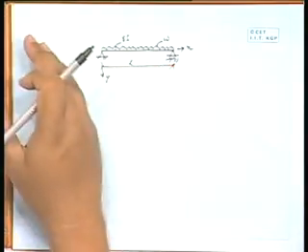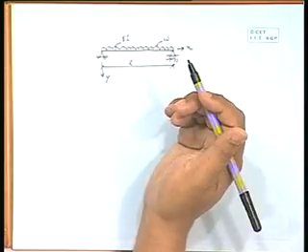We were trying to proceed from the free end. We need not bother how much will be the reaction at the supports. But here we can start from this end or the other end, both ends are supported. So first job is you have to find out the reaction, and that will be utilized for finding out the bending moment expression, and that will go to the differential equation.